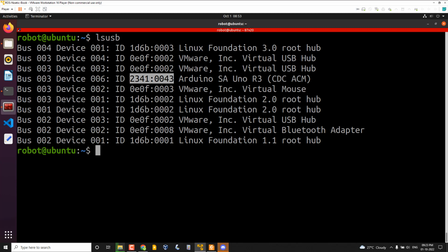Yeah. So the question is, do we have to do this for the Raspberry Pi? Yeah, it is available in all Linux systems, so it will be better to assign the permission on the Raspberry Pi as well. Also, you can change the device file name. Instead of ttyACM0, you can redirect that to ttyArduino. So we can do this kind of remapping and also the permission.